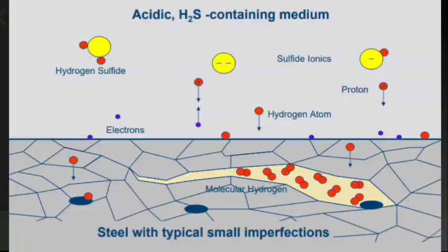Okay, first let me answer this and after that you can ask other questions as well. So basically when it is in the sour environment, that is when the process fluid is containing H2S with water, then we will go for this HIC testing, especially for plates. Pipes, yes, seamless pipes only. When you are controlling the sulfur content to less than 0.01 weight%, then that becomes a resistant material. There is no tendency for cracking due to HIC.